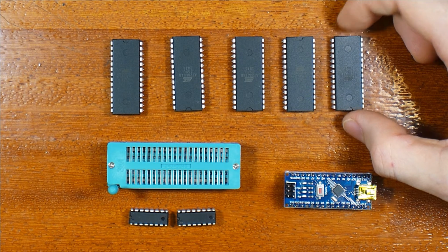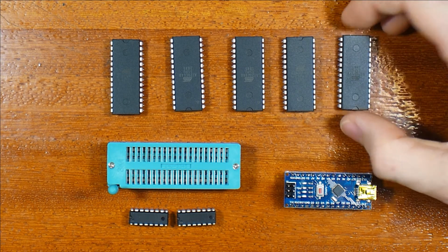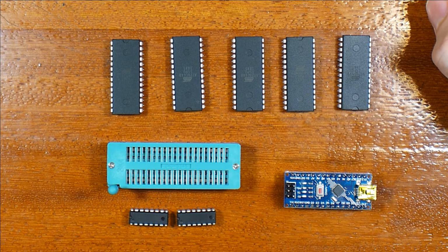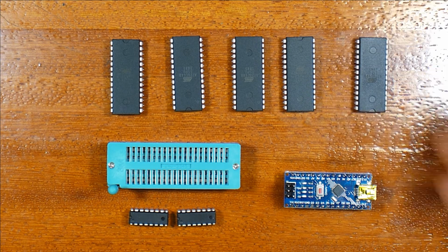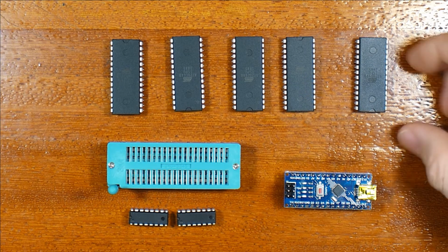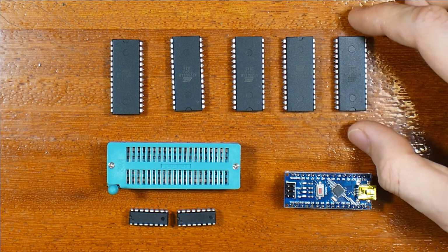And we transform this EEPROM into a lookup table. We program it with the output respective to the input from the address, and we put there what we want the output to be. So we can replace any combinational circuit with this limitation of 8 outputs per chip, and depending on the memory size, also the inputs.